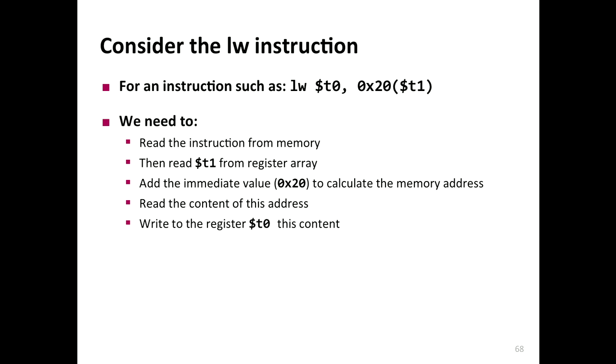So let's start with the longest instruction, load word. And you know that we have the base plus offset addressing, and this is the destination register. We need to basically do all of this. This is basically the steps that load word needs: fetch instruction, read operands, evaluate address, access memory, store result. Right.